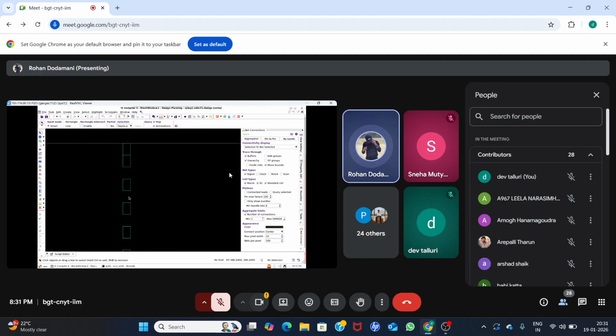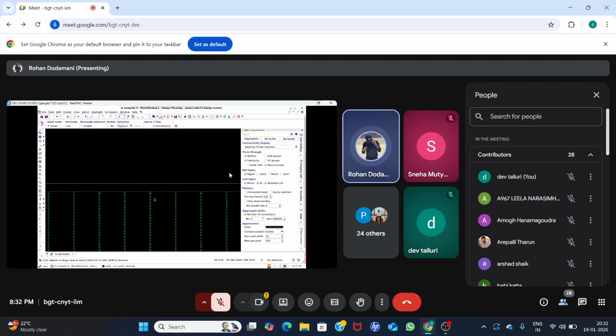In this space one VDD goes and one VSS goes. In between VDD and VSS, the tap cell will be preventing the two nets. For this we can easily prevent the latch up issue. There is a chance of a low resistive path being created between VDD and VSS, so this tap cell will avoid that path. So this is how we need to do it.